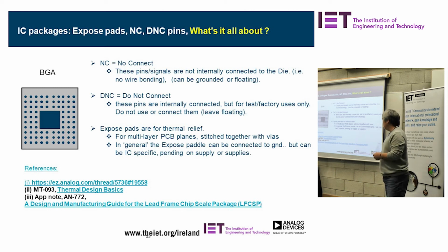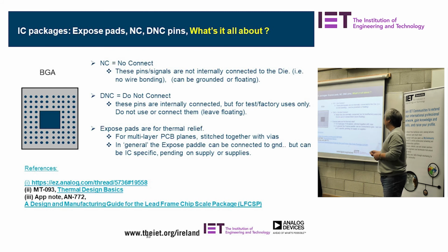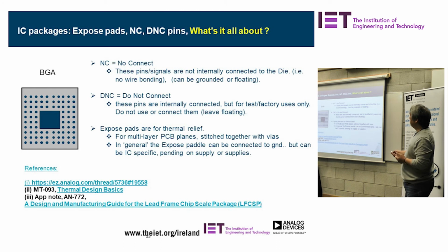And why they don't need to be connected. I just tell people that no connect means do not connect it. DNC, do not connect at all. Because they use it for test cases, sometimes these pins are internally connected. So sometimes when they say no connect, that means it's not internally connected, it's not a bonded wire, so you can do what you like.